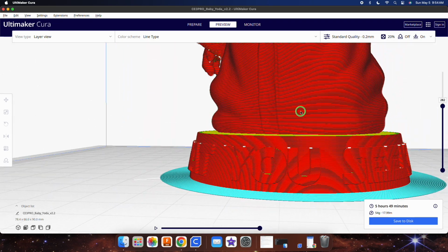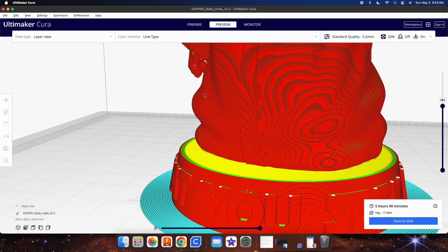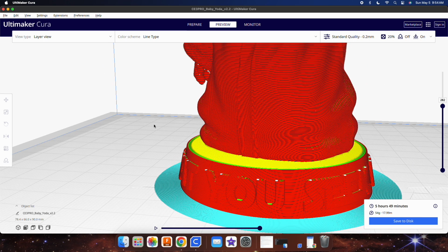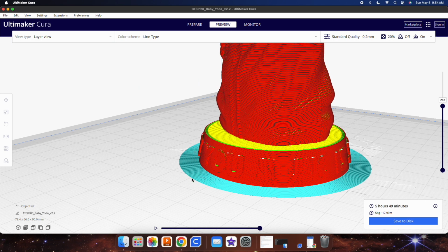So the brim just acts as a tiny little layer that you can peel off or cut off sometimes, and it helps just hold it down a little bit. It does serve, again, to prime the nozzle before it gets started, but mostly what it does is, it holds it down. So if it gets to a point where it wants to start warping, then it'll be like, no. And then, the sides of the brim might go a little bit, but the brim is going to be removed anyway, so it doesn't really matter.